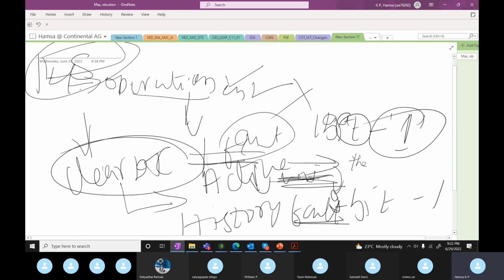Now, due to more air or something, the blockage has been moved, so the condition has been removed. The fault that was set in the current ignition cycle or operation cycle will be moved to the history fault, because the fault condition is cleared. The fault condition is not present now. The ECU is able to receive the inputs from the camera again because the blockage has been removed.